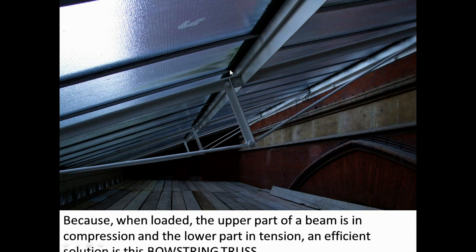Here we've got a T-section steel upper member. That's in pure compression. But the lower part of this beam is now in pure tension, isn't it? This is just a rod. So it's in tension at the bottom, it's in compression at the top.